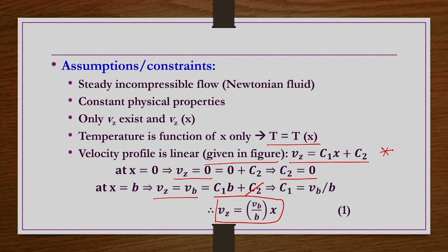So, even if the boundary condition of the moving surface has been changed for temperature, the velocity profile is not being affected. What does it mean in these problems? The velocity profile is affecting the temperature profile, but the change in temperature, the non-isothermality in the system, is not affecting the velocity profile. Neither is the rheology of the fluid affecting the velocity profile, because of the narrow gap it is having. So, because of the flow, the temperature profile is changing, that we are measuring now.